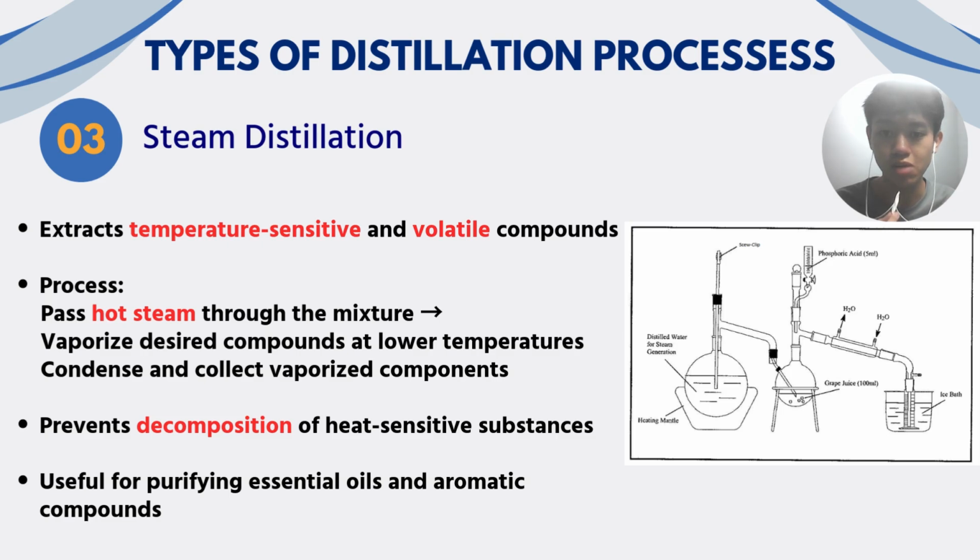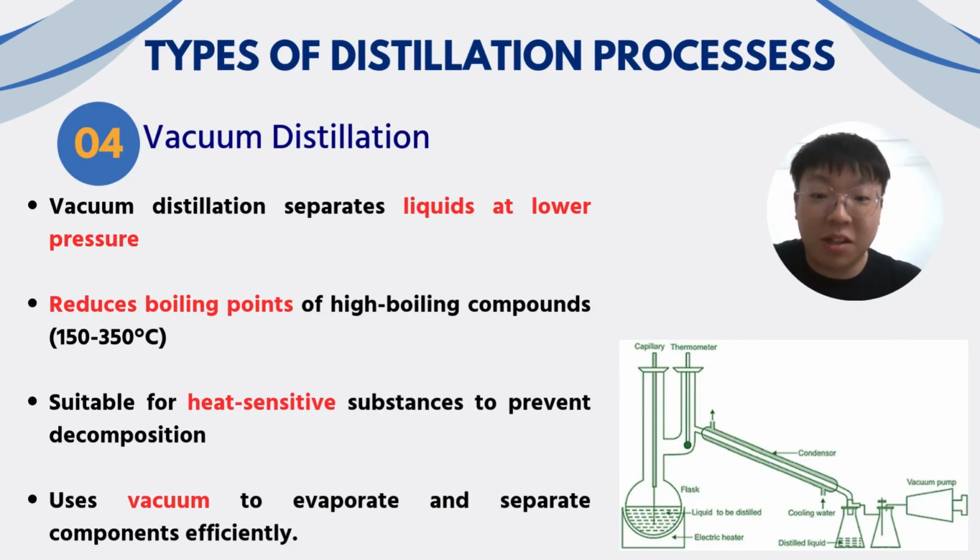Vacuum distillation is a technique to separate liquids with very high boiling points by lowering the pressure. This reduces the boiling point, making separation energy efficient and preventing heat-sensitive substances from decomposing. It is widely used for purifying chemicals safely and effectively.